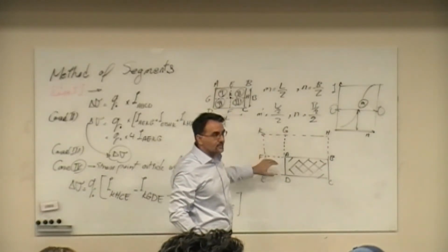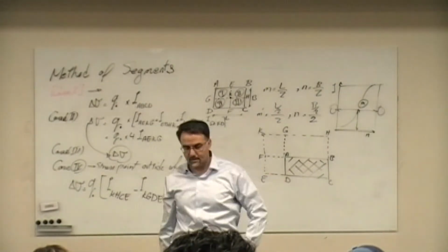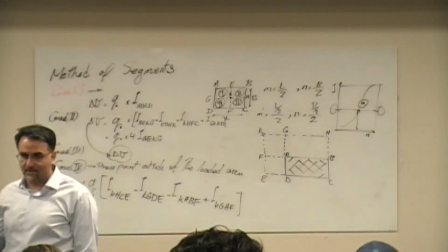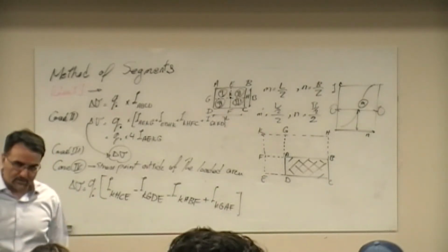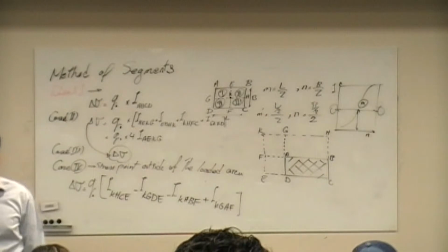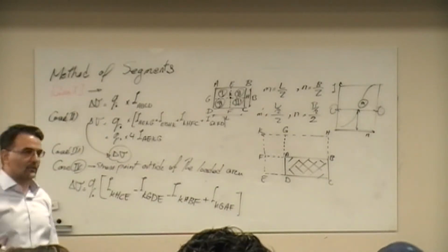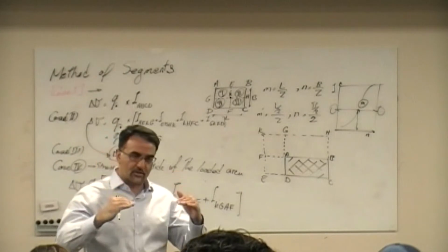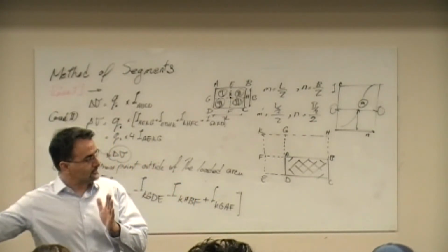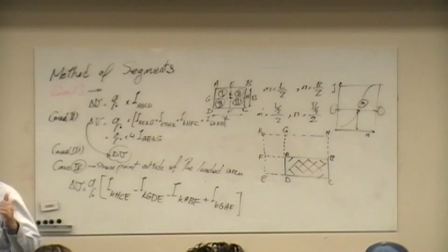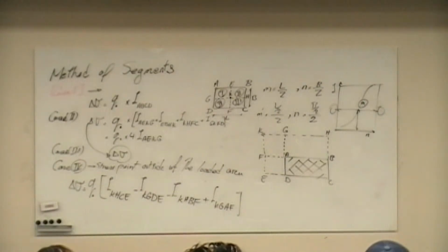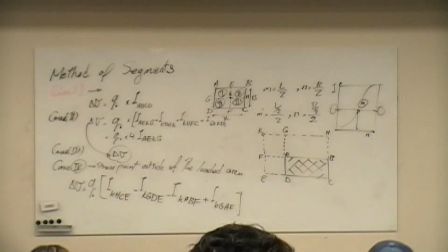So they're different. The only thing that is different in each of these influence factors are the length and the width. The Z value, or the depth that you're interested to do the calculations at, is constant, right? Because, for instance, you want to calculate the stresses at 2 meters below the surface, 5 meters outside of the rectangular shape footing that we have, right? So this is what we can do instead of using those spreadsheets that we have posted on the website. For your homework assignment, you're going to use this method of segments to be able to do the calculations.